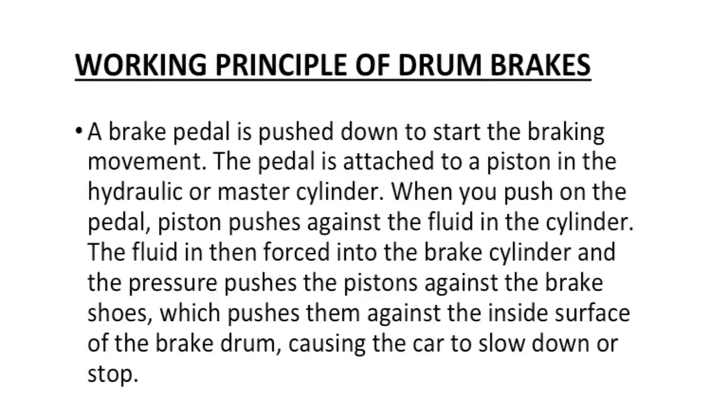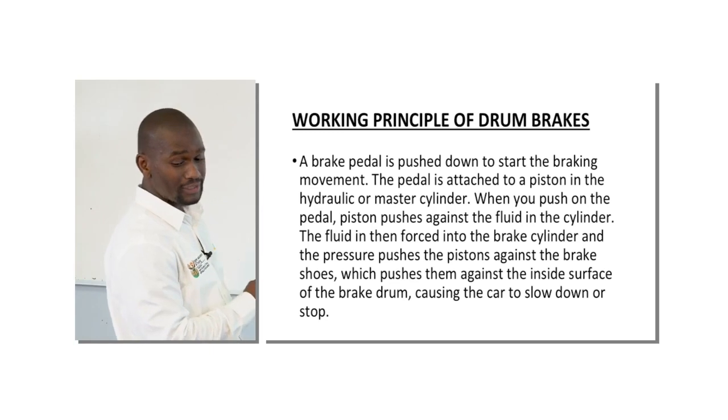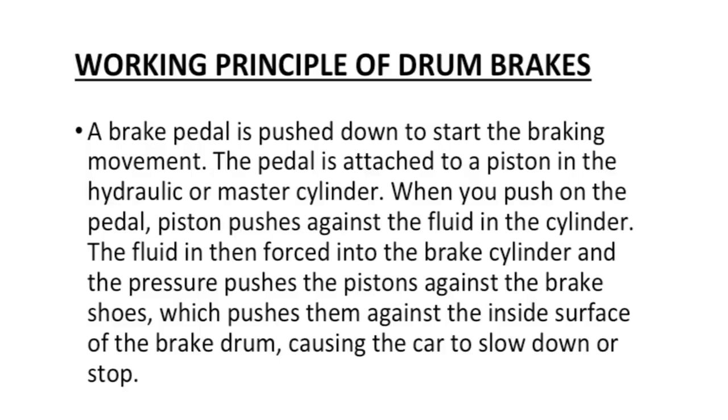Then the working principle of a drum brake. A brake pedal is pushed down to start the braking movement. The pedal is attached to a piston in the hydraulic or master cylinder.